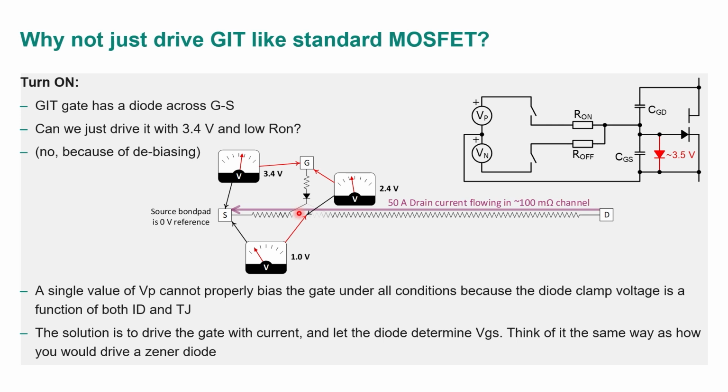If I have a lot of current, it could be like a volt. Conversely, if I'm going the other direction, in third quadrant conduction, now this could be at -1. So here's the problem: how do I correctly drive the VGS when I have this variable below the gate that I need? That's what I really want to drive, and it can vary by ±1.